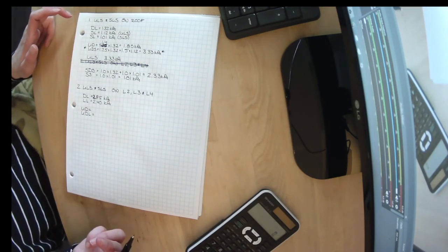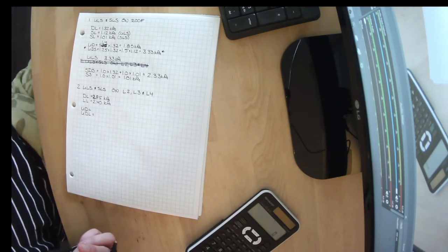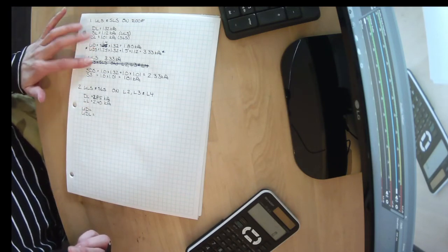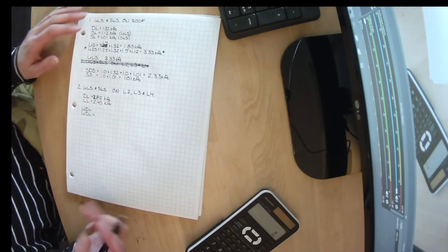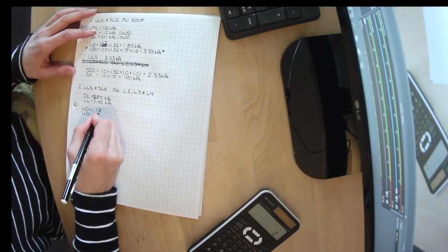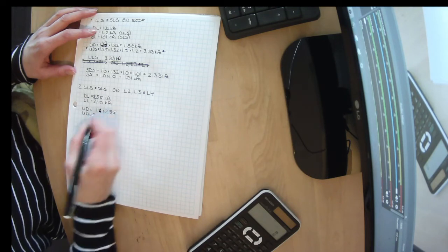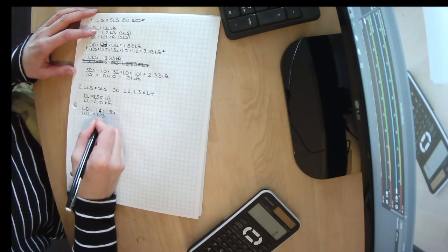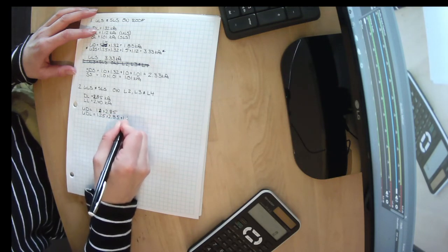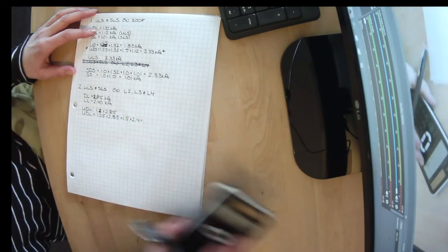So we don't really need to write that down. This is where getting good at it, you get to eliminate some things. If we had dead and snow, or if we had live on our roof, we would have more combinations we needed to look at. So 1.4 times 2.85, or 1.25 times 2.85 plus 1.5 times 2.4.